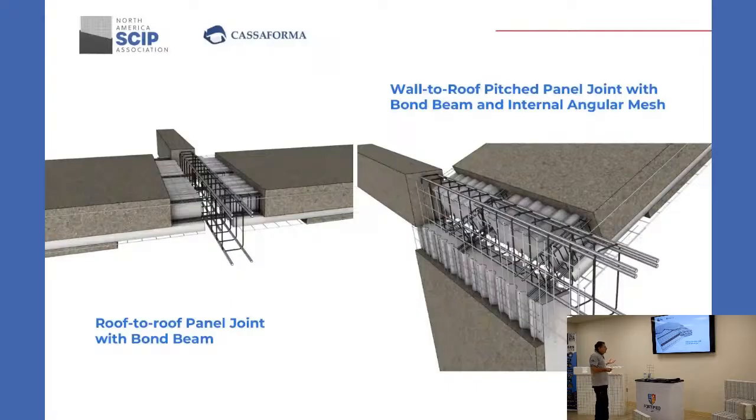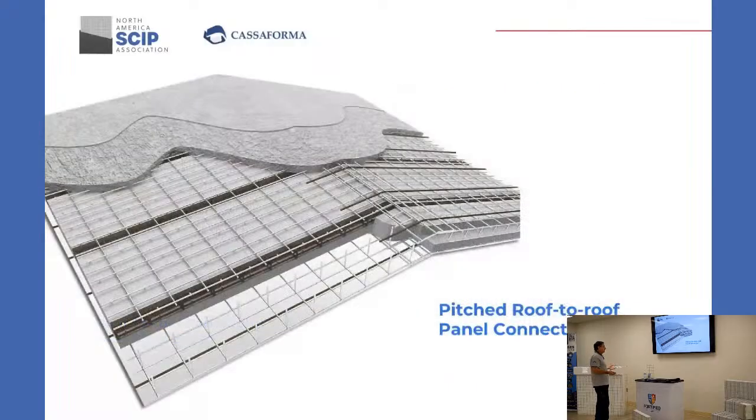Well, here we see it on a pitched roof. The only thing about the pitched roof is that, of course, we have to consider the slump we are working with on the concrete, depending on the pitch that we have. So there might be times that, to achieve that, we have to work in different strips and place ribbons in the middle. We put one, then another and another, depending on the slope that we have.